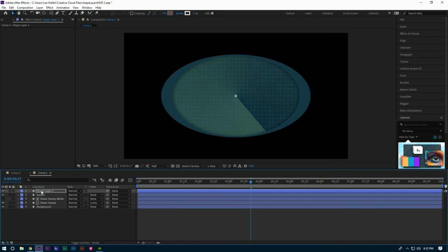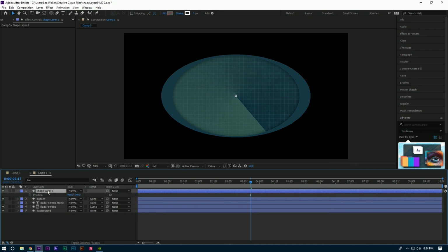We can go ahead and animate that. I'm going to select that layer and hit P on the keyboard for position. And I'm going to just scrub this off to the side a little bit. I'm holding down the Shift key as I scrub that number. Bring it up a little bit, just set it off right in there. Make sure that my timeline indicator is at the beginning of the timeline.